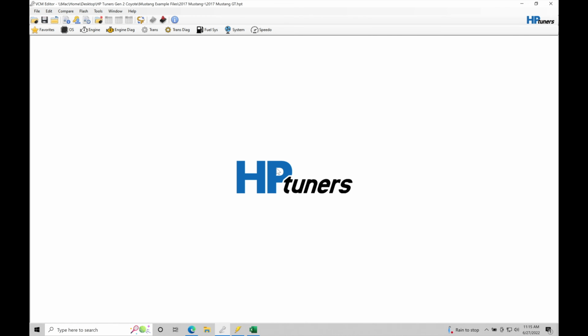I just want to make sure that this topic is thoroughly gone through so you understand what is going on here, because the variable cam control calls on for spark timing, for our torque model, for our speed density, among many other things. These are different modes, or what's called map points, we can transition through, all based on the variable cam control's movement. So depending how our cam pairing, both the intake and exhaust cam, as they're rotating and dialing in or out overlap as we're driving, it's constantly shifting through all these different operation points called map points in our engine control module's operation, and we need to understand what's going on with that. It is a critical role in order to actually calibrate or tune your Gen 2 Coyote.